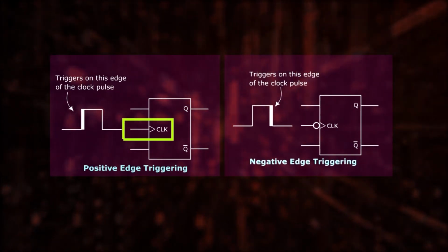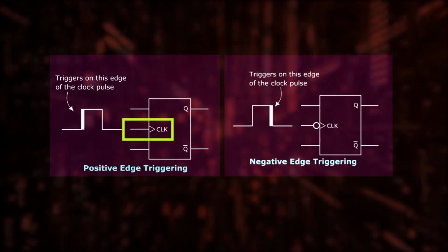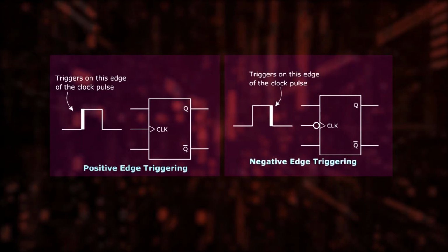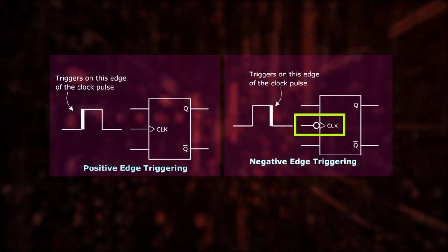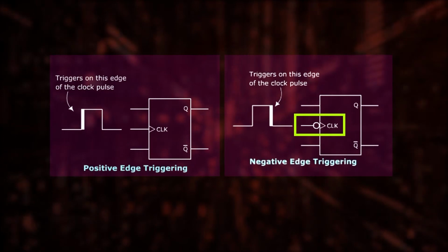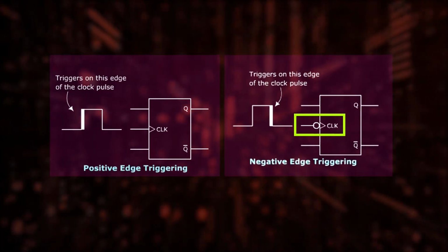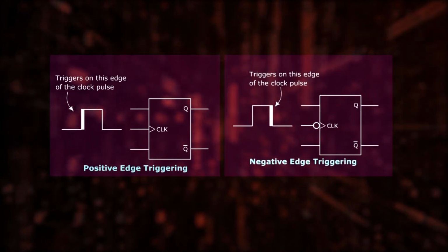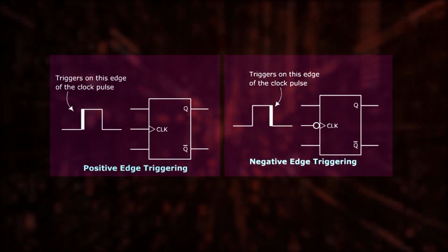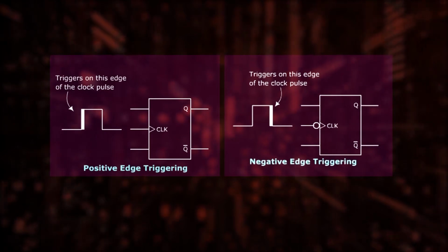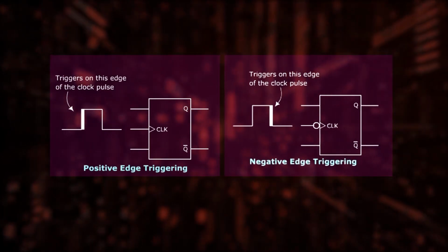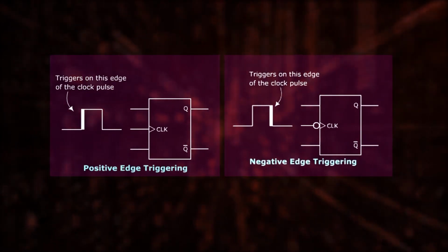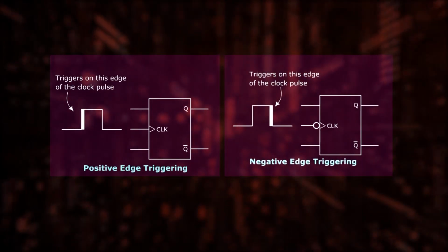If you notice only an arrow depicting the clock pulse, it is a positive edge triggered flip-flop. Or if you find a circle attached to the bottom of the arrowhead of the clock pulse, it is a negative edge triggered flip-flop. You might have observed that the clock pulse is changing its levels at discrete intervals which are of the same duration. This explains the reason for the flip-flops being stable in predicting their next stage of output.